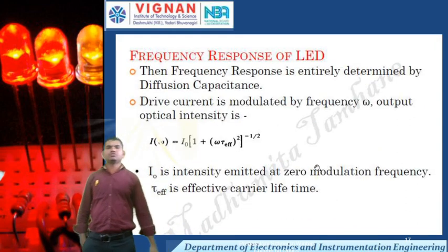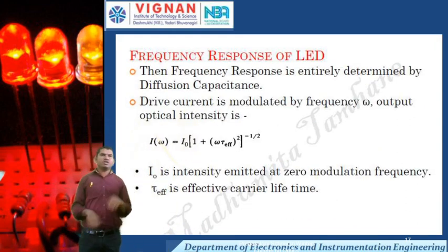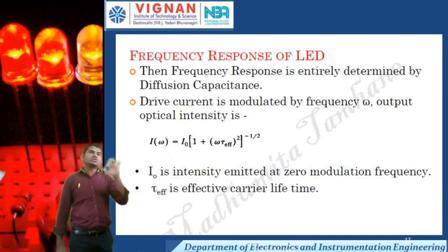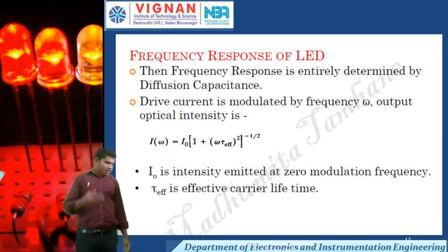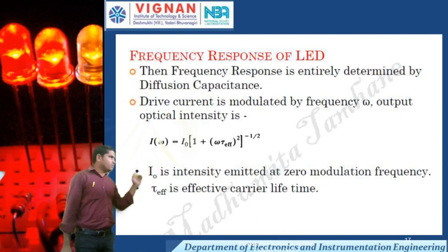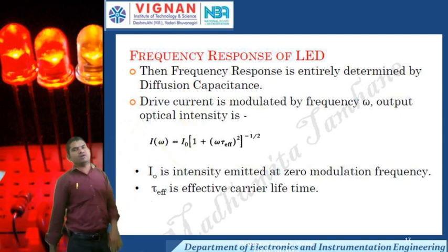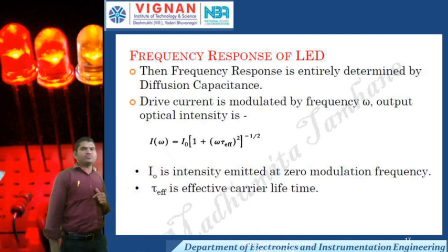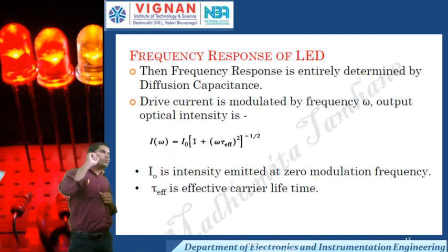Now, frequency response of LED. What is the frequency response of the LED? The frequency response is entirely determined by the diffusion capacitance. If we calculate the diffusion capacitance, that is directly proportional to the frequency of the LED. The drive current is modulated by the frequency omega.